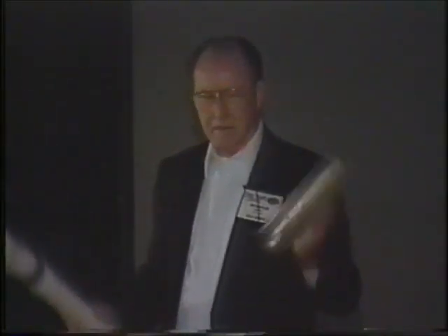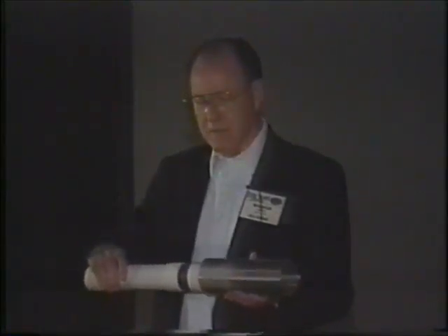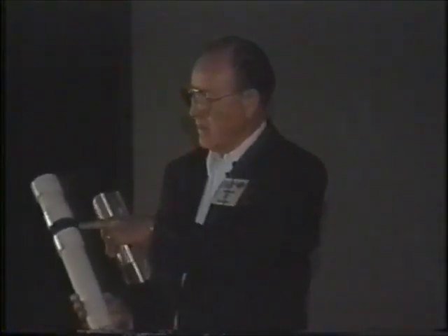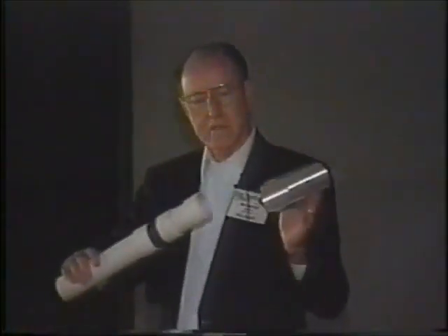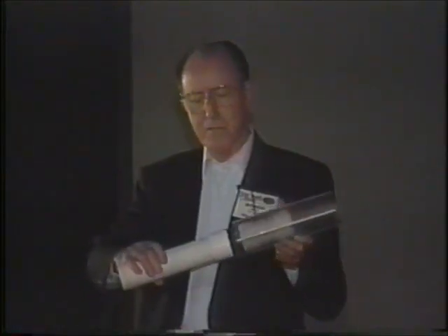So this is your L1 coil, L2 coil, and the way we're going to do this is PVC, and I cut a collar here so that I could slide it on there and use it for a spacer and put another one there as a spacer, and the net result is that this thing fits almost perfectly. It slides in and out of this particular coil here. Now, this is one way to tune these things without having to figure all of the other characteristics that have to go into it.